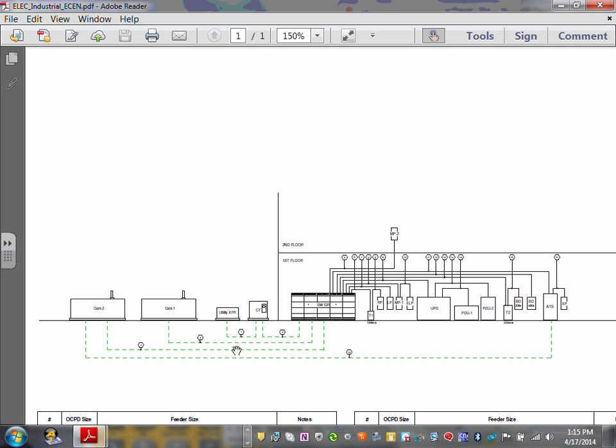But there are other buildings, guys. You walk in, and 208/120 will be the most efficient. The cutoff is 15,000 square feet or less. Your office building, 15,000 square feet or less, ideally is a good application for 208/120. More than 15,000 square feet, ideally it's a good application for 480/277.